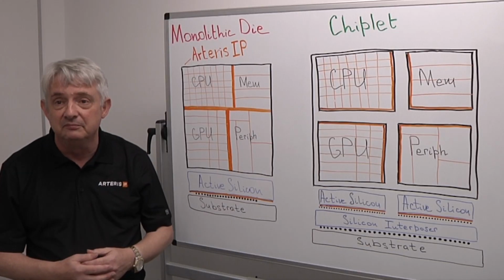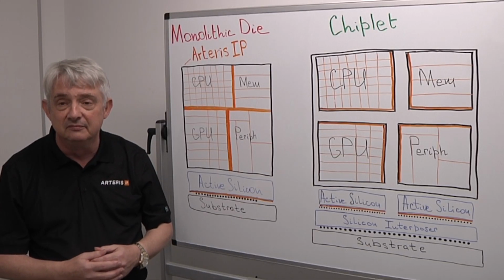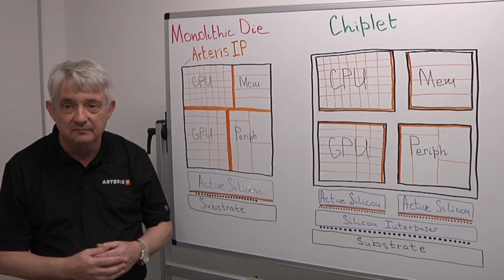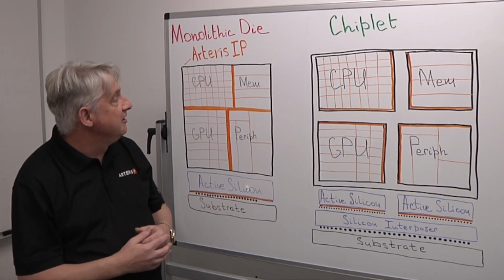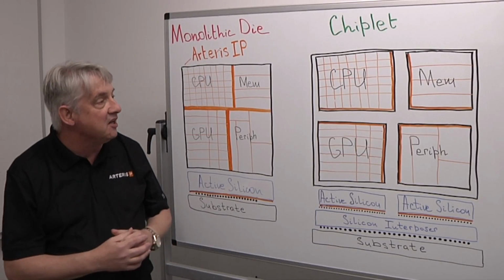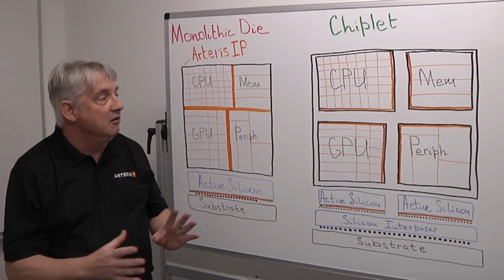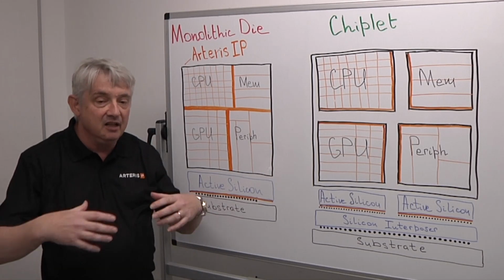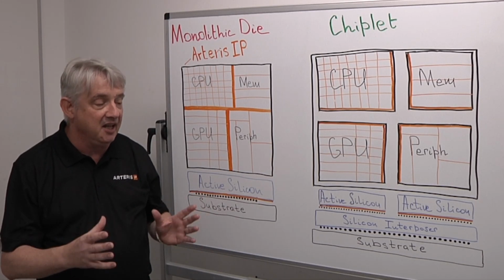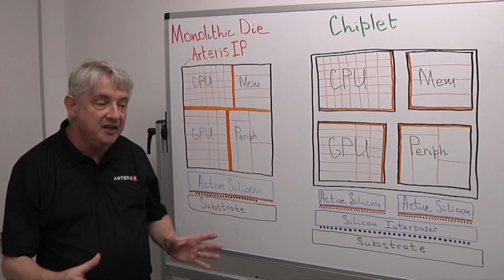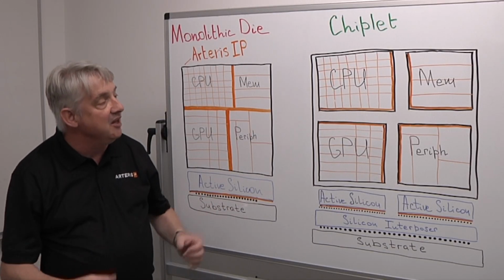But now what you have to figure out as you're developing these is, what is your workload going to be? How are you going to utilize this? So do I need more than one CPU? Do I need more than one GPU, right? Yeah, so you have to partition your design across your chiplets. I think typically most people today are designing individual chiplets as almost like separate projects, and they put them together. They verify them together in an environment, and they build the whole thing.